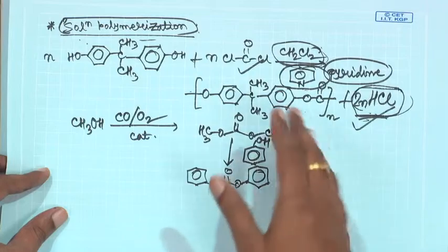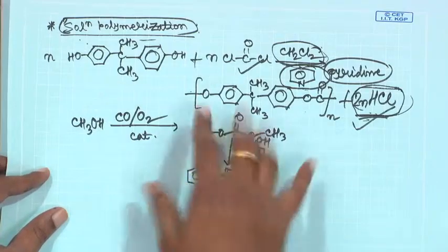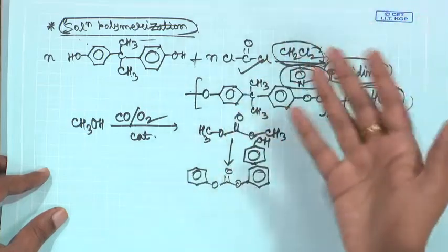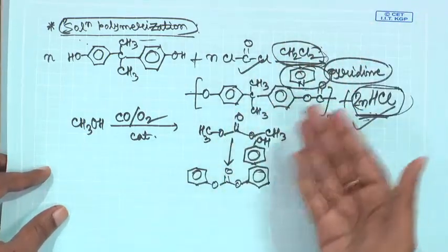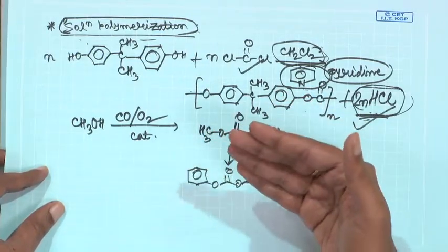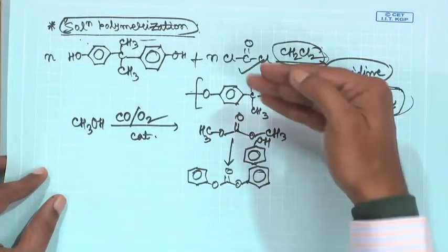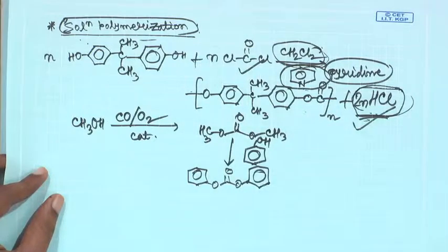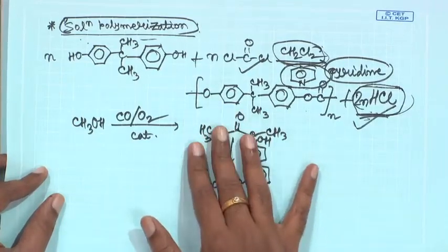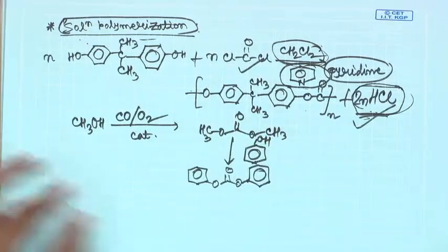And also if you have aromatic rings in the system, if you compare with the aliphatic rings, that gives you a higher impact strength of the material. And also we talked about the heat resistance, because that is another way of saying the preservation of properties up to a higher temperature. That means the heat resistance is quite higher if you have a higher Tg, or the glass transition temperature. And also these bisphenol A based polycarbonates typically have very good transparency, because they are amorphous materials.